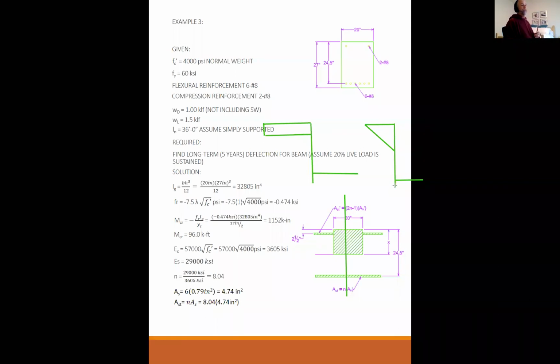As the beam continues to crack and strain, the neutral axis rises up. Oh, that makes a lot of sense. Perfect sense. Thank you for clarifying that. No problem, thank you for asking. So this is the plastic state, the homework that you're doing. This is an elastic state that we're assuming for deflections. The lecture is on serviceability. We're not factoring our loads. We're looking at the real loads and trying to calculate deflections. But homework number 4 is calculating total strength just before the whole thing falls apart.